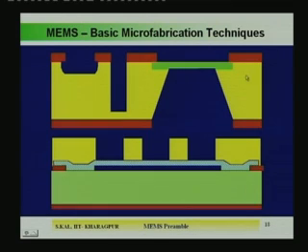Here the yellow colored piece is basically silicon, the red color is the passivation layer, and the green colored thing here is the etched top layer. So, that means there are techniques by which the etch can be stopped automatically. That I will discuss in detail in the micromachining lecture. And now, depending on the size of the opening of the passivation layer, you can get different kinds of structure from silicon itself. And the bottom picture is taken after surface micromachining of silicon.